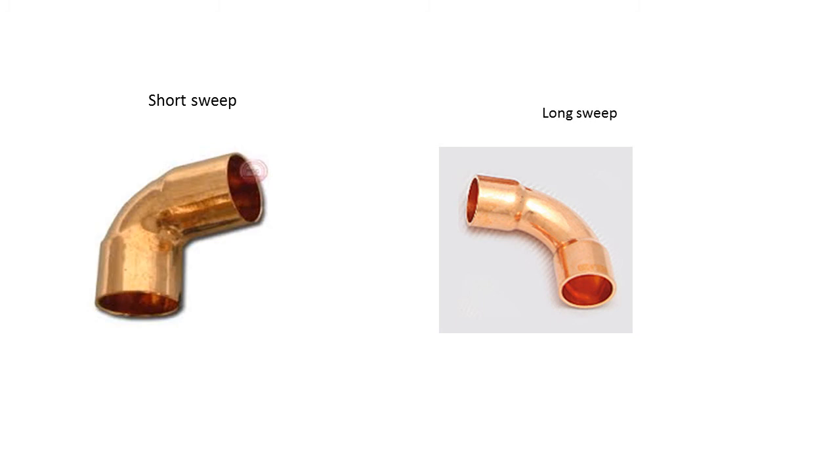The only difference pretty much between ACR fittings and plumbing and heating fittings is really just the 90-degree fitting, also referred to as an elbow. In ACR we use long sweep elbows. In plumbing we use short sweep elbows. This is due to the fact that we have very little tolerance for any kind of pressure drop in refrigeration. So definitely we want to use long sweep elbows in refrigeration and air conditioning.